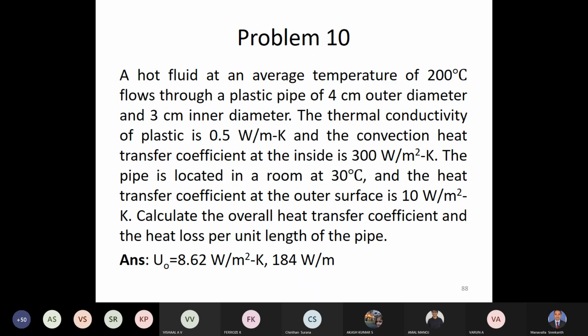Therefore, the time taken to produce hot water will keep on increasing. Then you will have to remove that scale. So that is called fouling. That can happen in heat exchangers in industrial applications also. That fouling will actually offer some resistance. On page 165, the table on top gives you different fouling resistances. But anyway, we will not consider fouling at this stage.